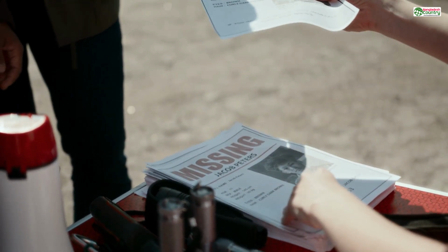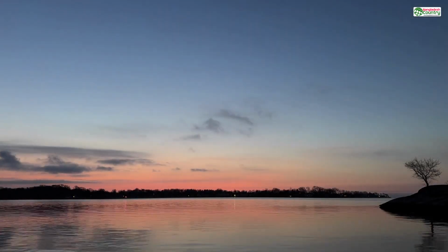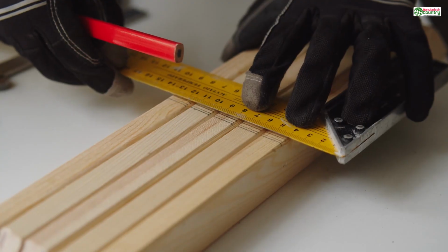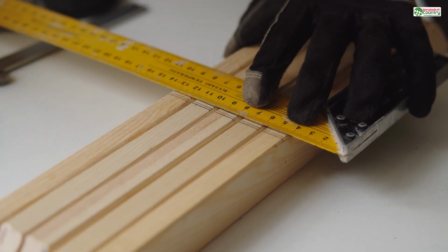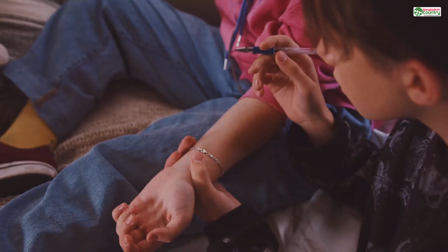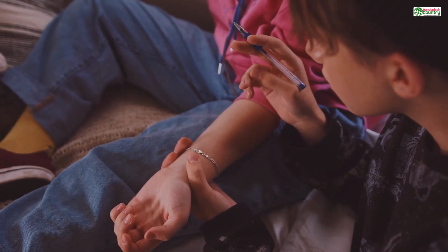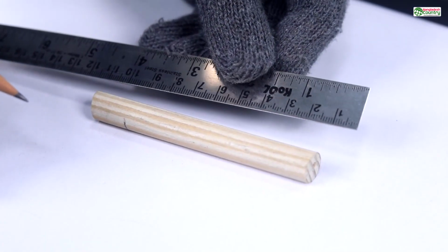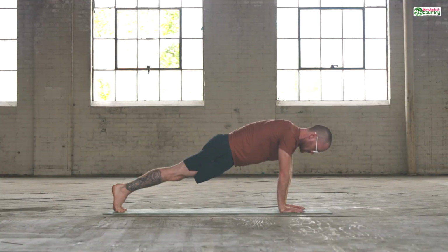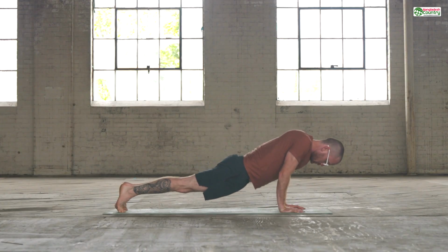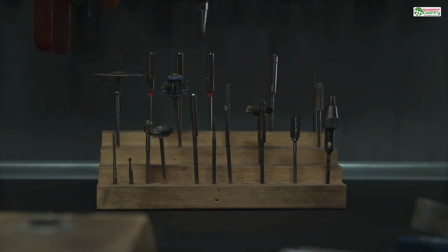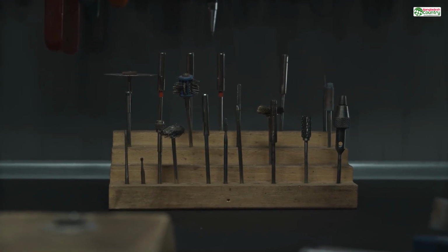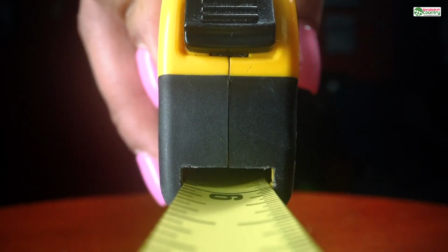First, set the unit system to metric. Second, set the length or unit of measure to millimeters. By doing this, you are creating a contract with your software. You're saying, from now on, when I type the number 1, I mean 1 millimeter. Not 1 meter. Not 1 inch. 1 millimeter. This simple act aligns your virtual world with the real world of the 3D printer. Now, the tools inside your software become infinitely more useful. The measurement tool, the ruler, the dimension guides, they all now speak the language of your final product.